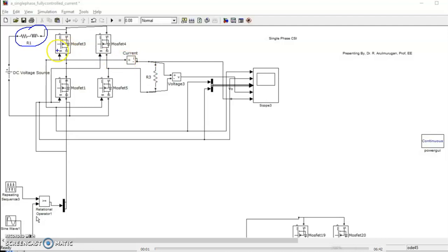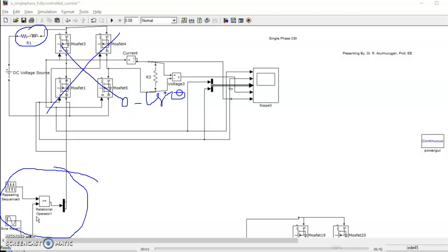Coming to that, this is the simplest diagram. As usual with the voltage source inverter, one inductance is connected in series with a resistance, and the resistance is very small. Then I gave it a value in Henry, and I gave pulse width modulation, left slash and right slash. I trigger it through the pulse width as usual, 0 to 180 and 180 to 360.